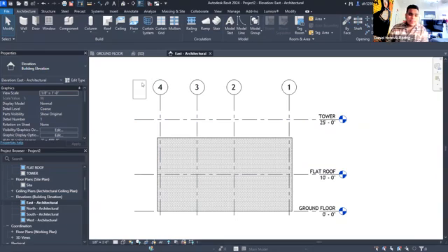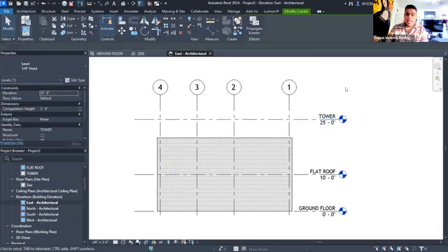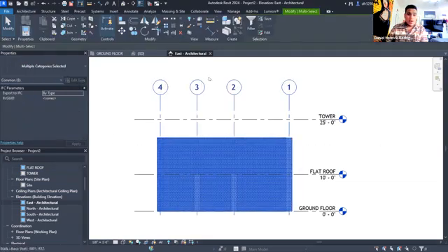If you select something from the left to the right, it's going to create this solid box that only selects things that are completely within this box, right? So I'm touching 4, 3, 2, 1, but I'm only completely enclosing tower, and that's why it's the only thing that it selects. As opposed to a box that comes from the right to the left that gets everything that it touches. As long as it touches it, it's selecting, right? So another option to select the walls here is going to be to just run across from the right to the left, and you're going to select a whole bunch of things.